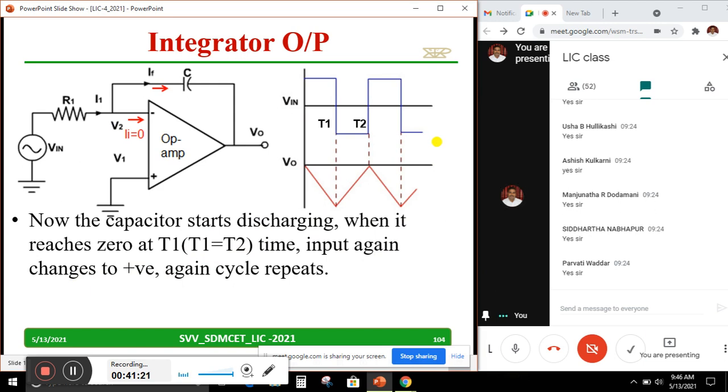And even in the interview, they will ask you to write an input and output, how it converts. Simply the students will write a square wave, they write a triangular. This line they put at the center, which is dangerous. Please try to understand this concept. And if T2 becomes greater than T1, then V0 voltage becomes positive.